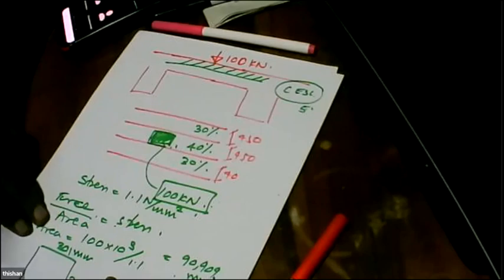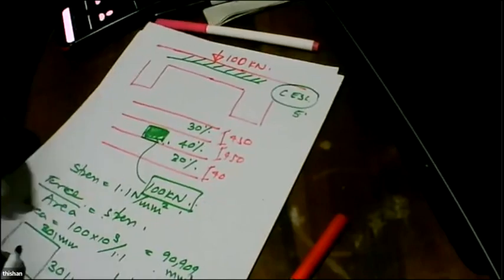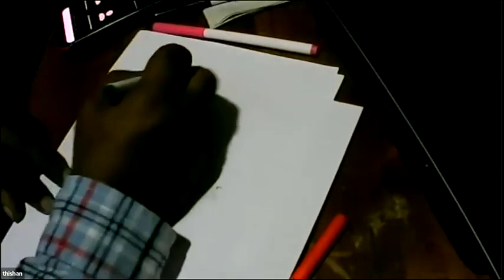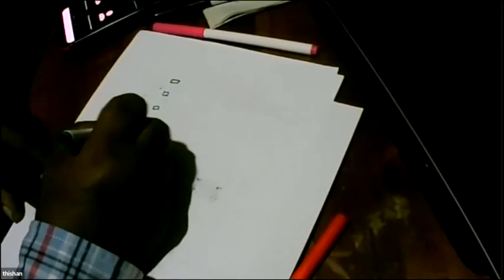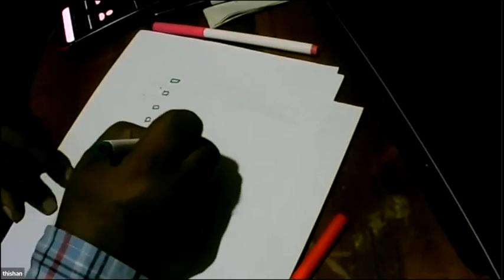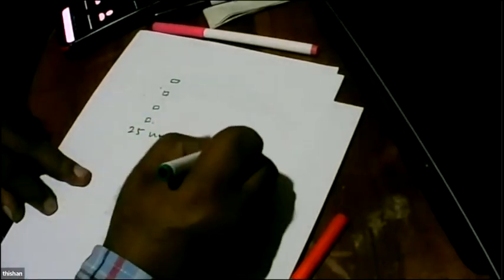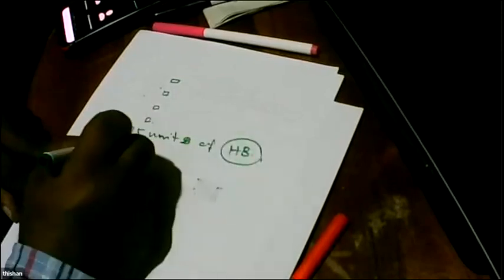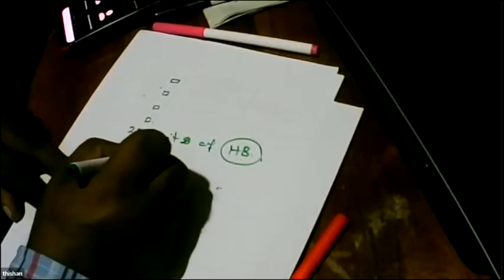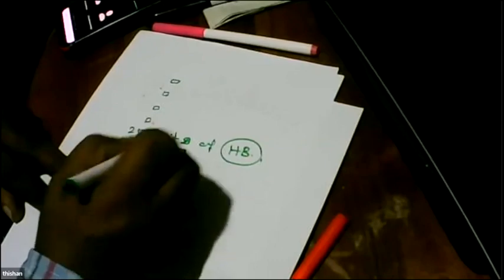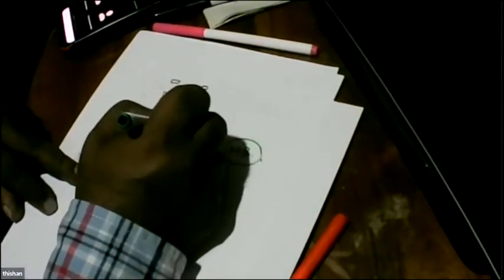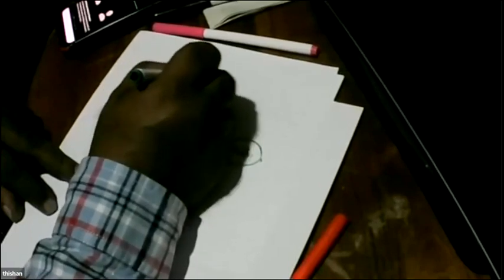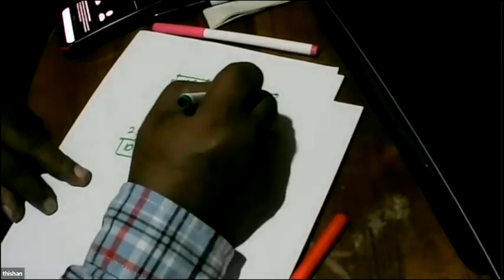That is, the HB vehicle. In addition to that, you can consider that this bridge will be subjected to 25 units of HB type loading, giving a total weight of 100 tons in a vehicle with 4 axles at 1.8 meter spacing, and this length can vary from 6 meters.